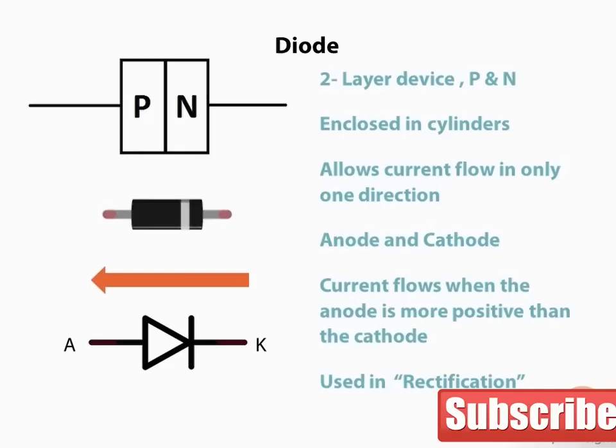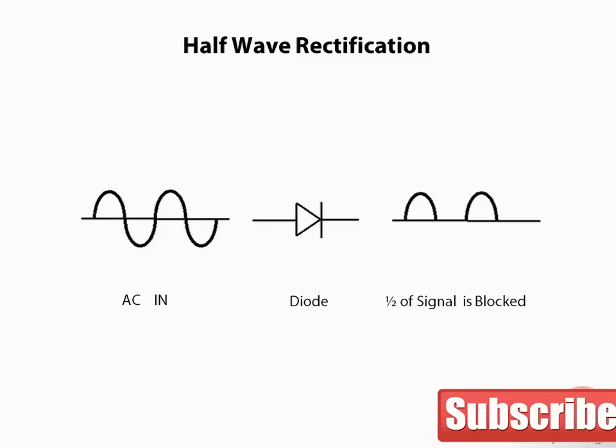There are two types of rectifier circuits. The first type is what is called a half-wave rectifier. It is called that because it only allows the positive values of an AC wave to pass. The negative portion is rejected or blocked, and the resultant output is half of the original wave. So moving from left to right in this diagram, we see the original AC signal. As it passes through the rectifier, which in this case is a single diode, it yields the modified waveform. This is a raw half-wave signal which can be further filtered and smoothed using RC circuits.